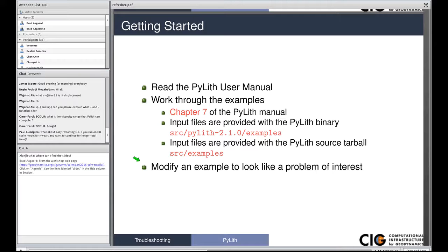Before I run an example, I'm going to answer Stephanie's question of what was the difference between the Lagrange multiplier approach and traction at split nodes. Generally, the fault implementation in PyLith is quite similar to other traction at split nodes techniques. It's really in the bookkeeping and our definition of what the Lagrange multiplier is and how that is used in formulating the equations that are solved.